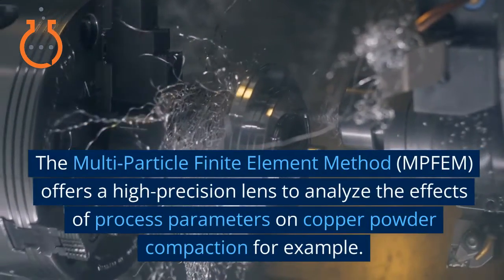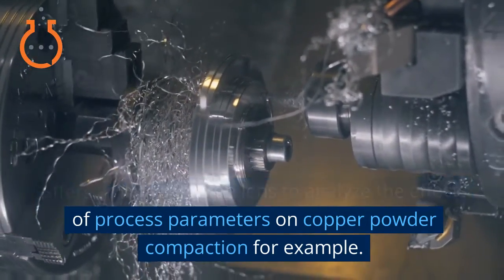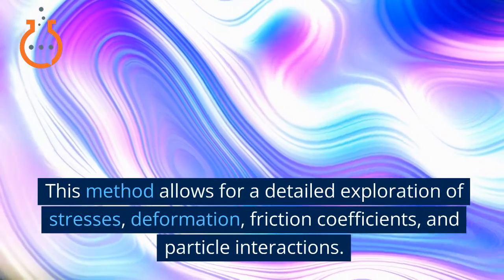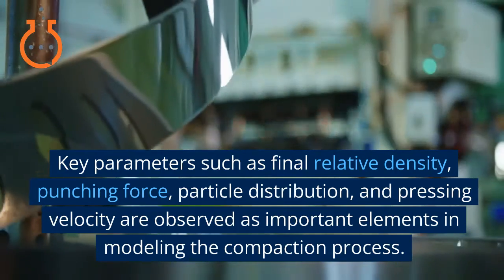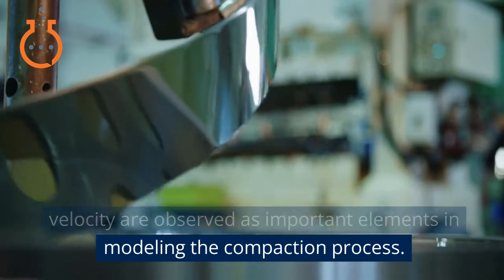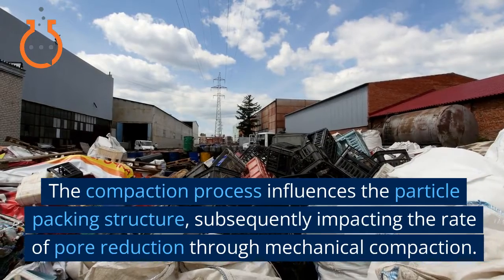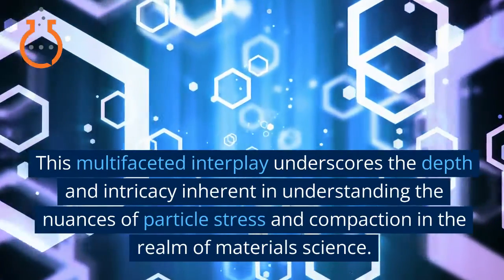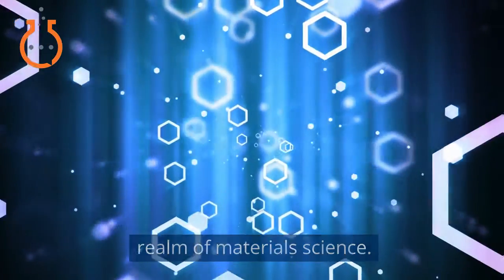The multi-particle finite element method, MPFEM, offers a high-precision lens to analyze the effects of process parameters on copper powder compaction, for example. This method allows for a detailed exploration of stresses, deformation, friction coefficients, and particle interactions. Key parameters such as final relative density, punching force, particle distribution, and pressing velocity are observed as important elements in modeling the compaction process. The compaction process influences the particle packing structure, subsequently impacting the rate of pore reduction through mechanical compaction. This multifaceted interplay underscores the depth and intricacy inherent in understanding the nuances of particle stress and compaction in the realm of materials science.